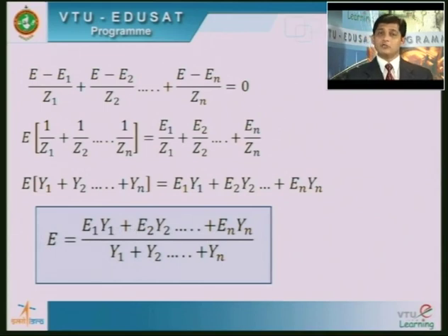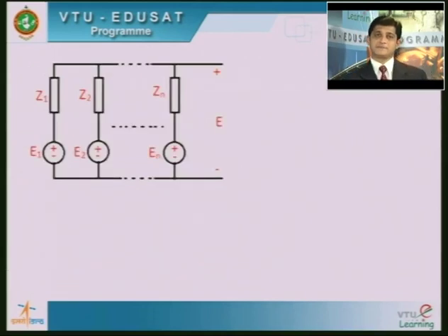Fine. Now, we also have to obtain the equation for one impedance which is there as the internal impedance with the one generator that we have obtained. Fine. So, how to obtain the equation for that? See here, since I have told you all these are internal impedances. If you cannot catch that point, you cannot say these are all in parallel. Since they are all internal impedances, we can say that Z1, Z2 up to Zn, all these impedances are connected in parallel. Okay. Since they are connected in parallel, how can we write the equivalent impedance across these two terminals?